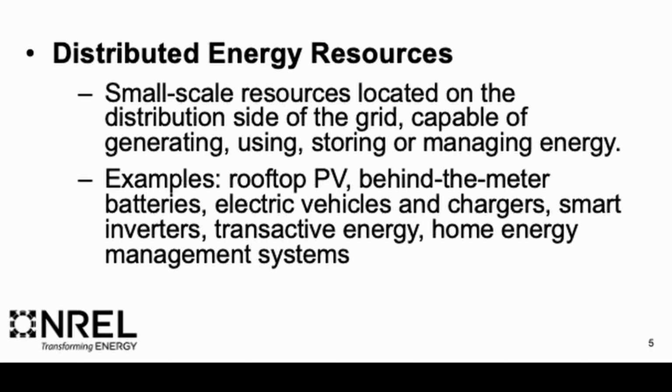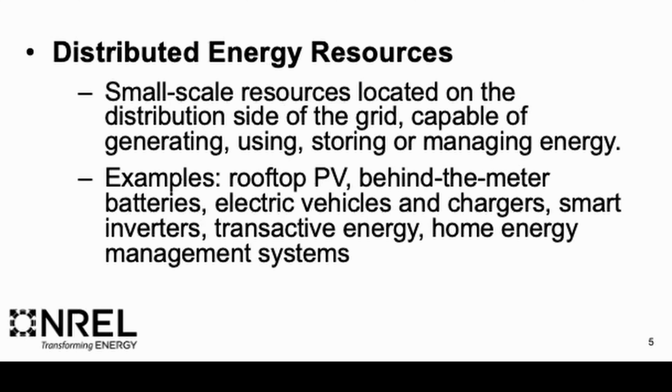These are widely diverse examples of distributed energy resources, but they include rooftop PV, behind-the-meter batteries, electric vehicles and chargers, smart inverters, which can provide special services for rooftop solar so that the panels are producing the right kind of power at the right time according to grid conditions.